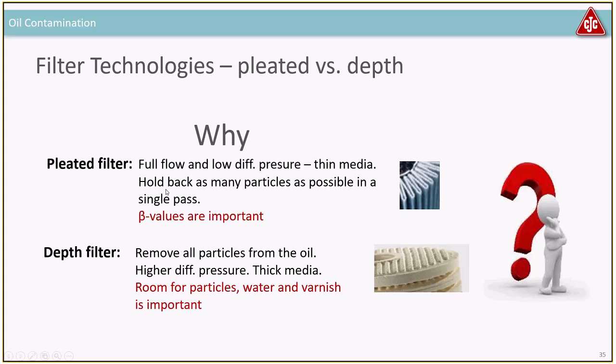Here in your pleated inline filter, you want the low differential pressure, and in your depth media, the kidney loop, it doesn't matter if the differential pressure is bigger because you have your own pump and you decide the flow rate.